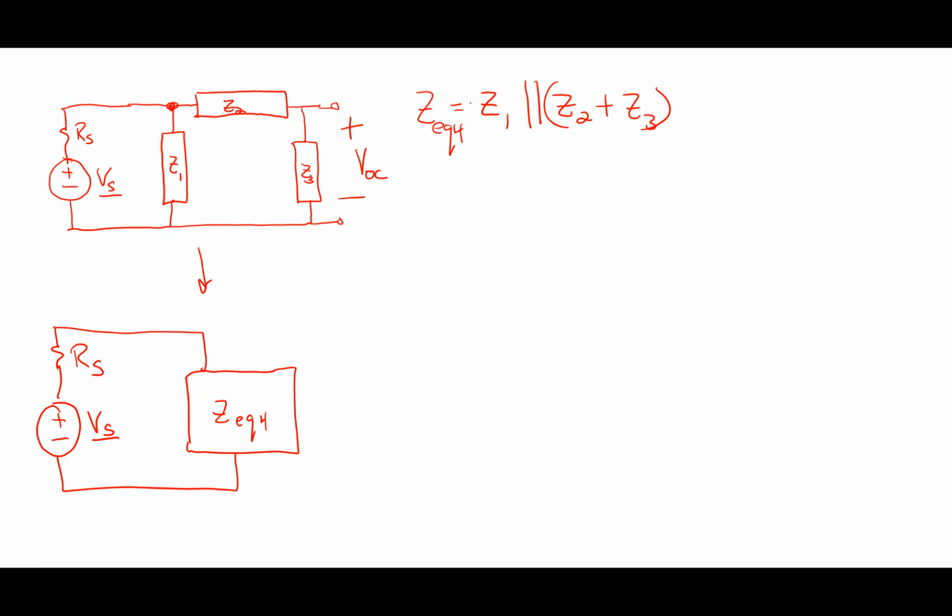Okay, so what's that going to tell me? That's going to tell me the voltage here, which I want to call V. To get that voltage across Z1, you need to make ZEQ for the whole other side. We can't just do a simple voltage divider for that V.